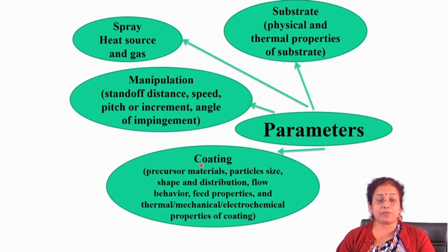Then manipulation is also very important, because that also gives you information about the coating strength and also the quality of the coating, the roughness of the coating, like stand off distance, speed of the manipulator, pitch or increment, angle of impingement.